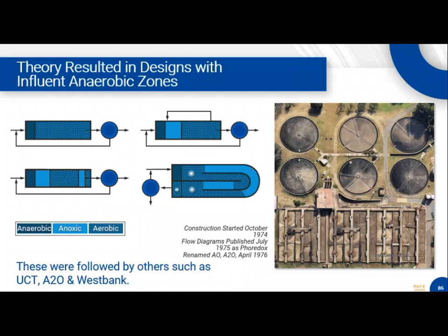Yeah, different loading, different characteristics. It used to be everybody had a big tank and you aerated it, right? But depending on your loadings and your wastewater characteristics, you may have to have a more or less complex bioreactor configuration to achieve the same effluent performance.